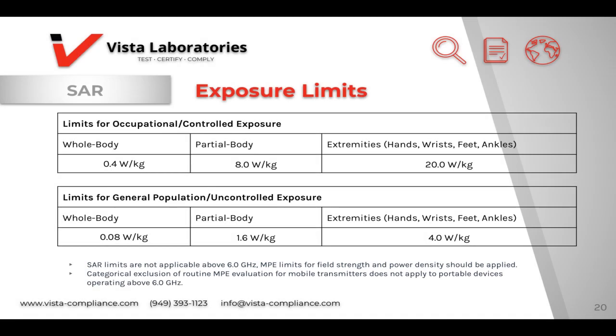So these are the exposure limits. These are the actual limits for SAR. And again, SAR is the basic fundamental reference exposure limit. So MPE, which we spoke about before, field strength and power density limits are derived from SAR. MPE limits have additional margins in them to ensure compliance with the SAR requirements. SAR needs to be evaluated using special tissue liquid or tissue medium.